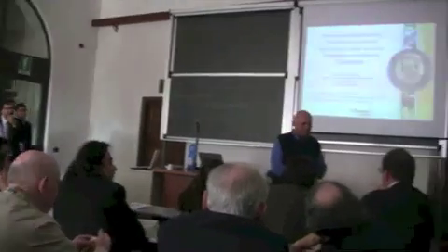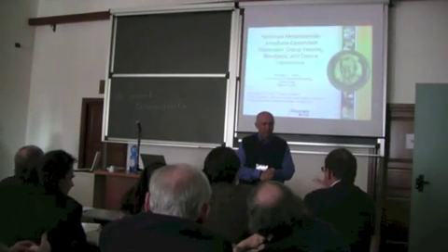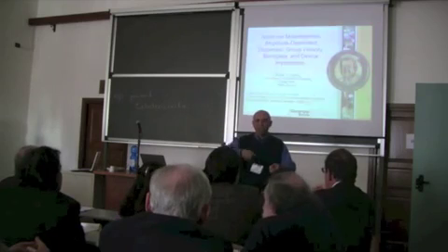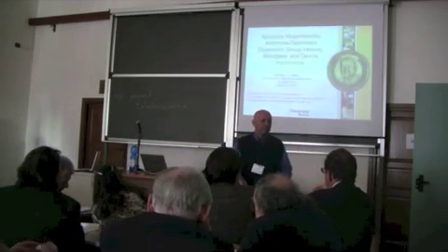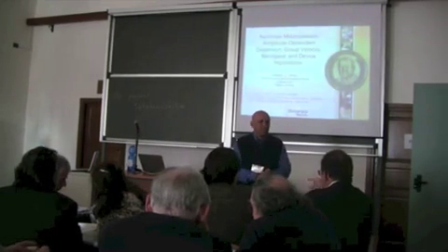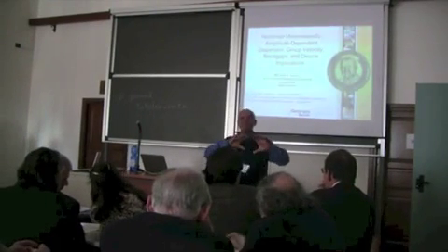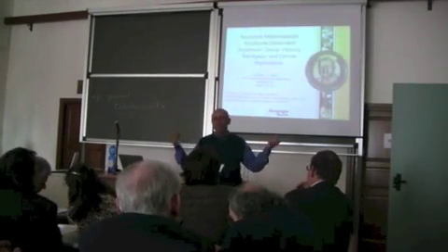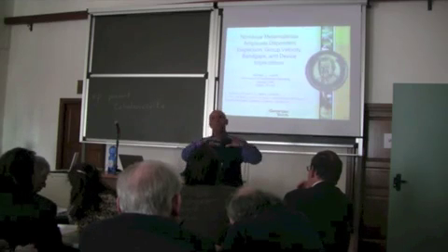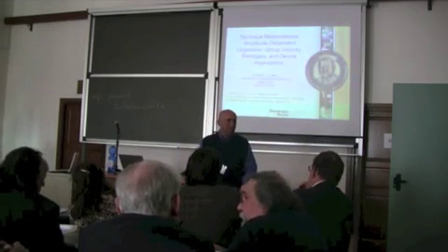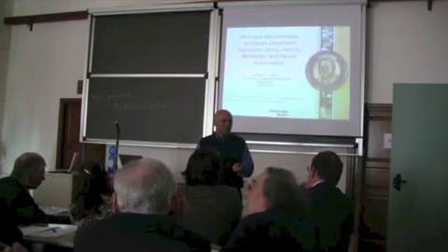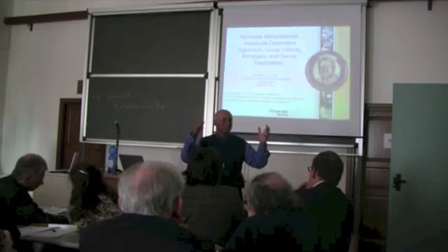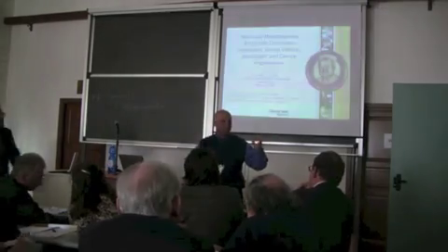Maybe I'm mistaken, but you presented some failure surfaces. Are there theoretical results about convexity properties of these? Okay, so what I presented are calculations, right? I calculate by going in different loading directions, and these are all numerical surfaces, so we have not looked into the convexity. The way these things are computed is just in a discrete fashion, so I have all these discrete points, and to show in the view graph, I make some interpolations. Also, how we determine these failure surfaces is an issue. Since we're doing numerical calculations, we have to decide what our failure criterion is, such as whether the acoustic tensor becomes singular.